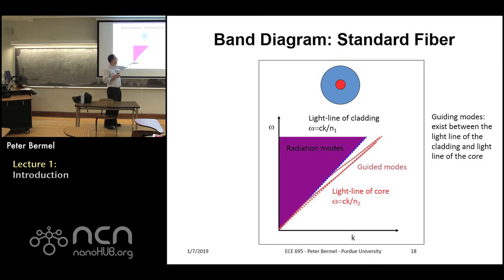But it also tells you that there are these other modes that are below what's called the light line. The light line is the point at which you have just achieved internal reflection. And there are modes below that internal reflection that are well guided within the core of the fiber optic, right? And you can see that as you go to higher V numbers, you start to get more and more of these modes. That's because as you go to higher frequencies, it goes to lower lambda naught and thus a higher V number.